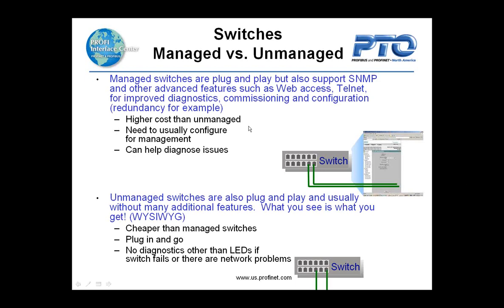There may be a little bit more cost to a managed switch, but a lot of times we recommend you use those so you can have that additional diagnostics. If you get unmanaged switches, they're plug and play, but they usually do not have many additional features. So what you see with those switches is what you get. You just plug them in and they go, but if something happens, the only diagnostics you have are the LEDs on the front of the switch. So if there's a light on and it's still green, but the network's not working, then maybe the switch went bad. You don't know those types of things, so it's harder to diagnose if there's a network problem.